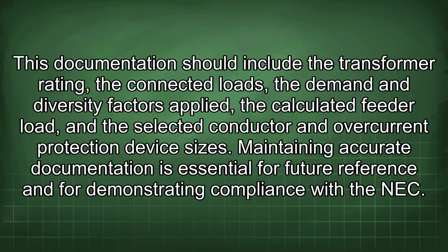This documentation should include the transformer rating, the connected loads, the demand and diversity factors applied, the calculated feeder load, and the selected conductor and overcurrent protection device sizes. Maintaining accurate documentation is essential for future reference and for demonstrating compliance with the NEC.